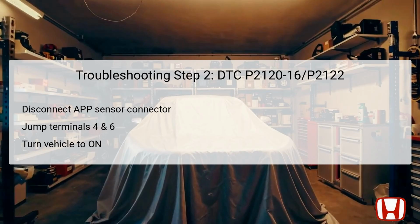If this occurs, it strongly indicates that the accelerator pedal module is defective and needs replacement. In the third troubleshooting step, the next phase is to disconnect the powertrain control module (PCM) connector, ensuring it does not interfere with ongoing tests. It's important to perform these checks after ensuring the APP sensor is disconnected.